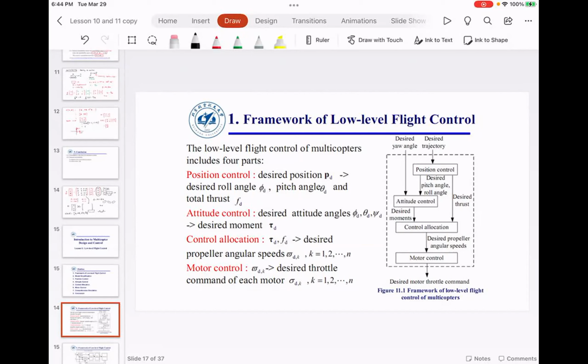I want this Mambo to hover steadily at one point. Clearly, when the Mambo is pitching down, the front two rotors should speed up. When the Mambo is rolling left or right, the appropriate rotors should speed up and slow down. What causes these rotors to speed up and slow down? The PWM supplied to these motors changes, and that changes the speed of those motors.